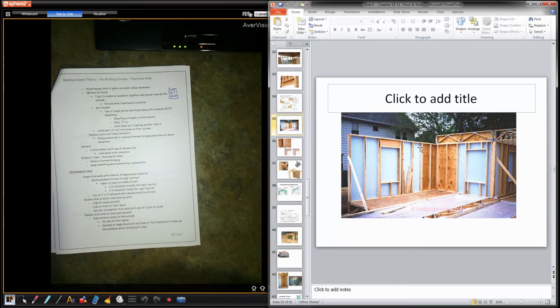So why is that there? To give lateral strength. Stop the wall from racking. Stop the wall from collapsing. Okay. You can see this is a truss style floor joist. So that is a truss going from this point to that point. That's why there's no lintel required here. The weight is bearing here and here. There's no weight there, so no point in having a lintel.